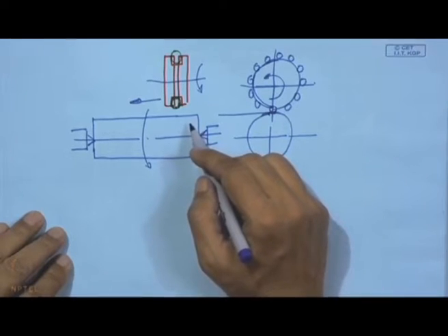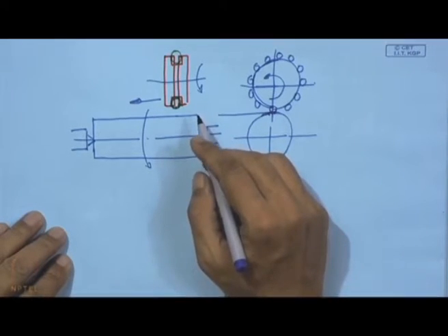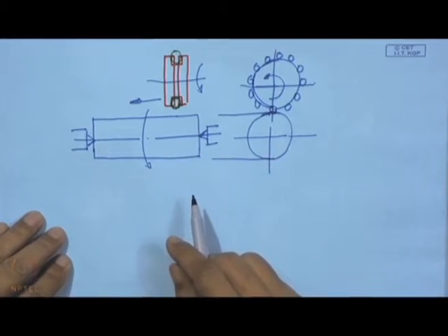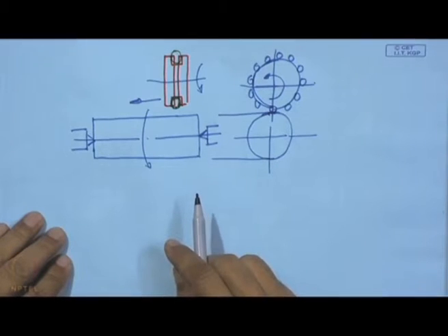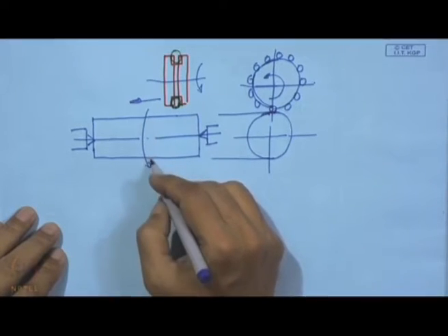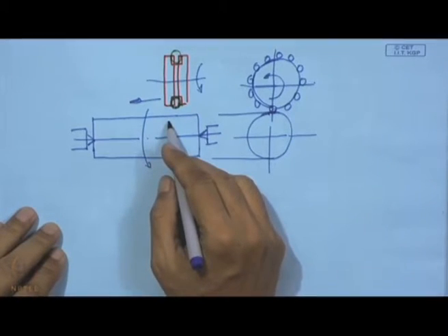Those grinding marks can be totally suppressed through this deformation, and more importantly, the greatest problem of grinding is the residual stress, and that residual stress can be well handled by this ball burnishing process, and we can also achieve a compressive residual stress over this surface.